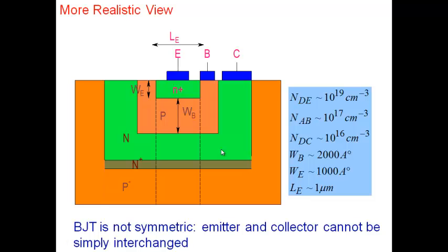We are not making an ohmic device. You're not making a resistor. So you don't want a resistance, you want a bipolar action from this particular device. So you would like to minimize the resistance, and one way of minimizing the resistance is to add an N plus layer here. So the electrons start from here, come down, and they go to the N plus. The N plus provides a nice high doping region, a highly conducting region, and the electrons can easily flow across here and then go up.